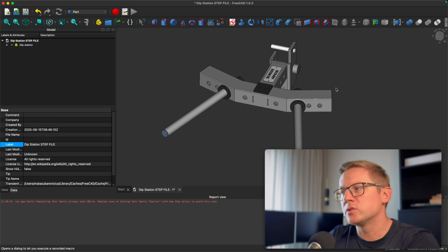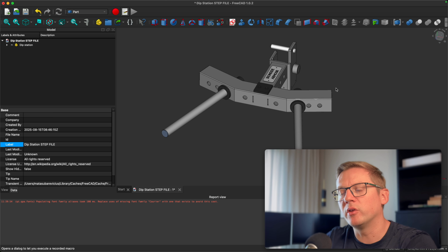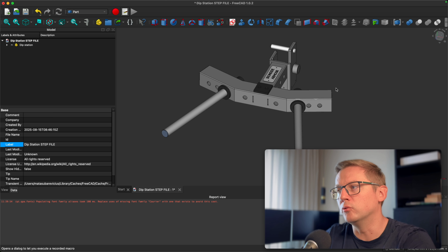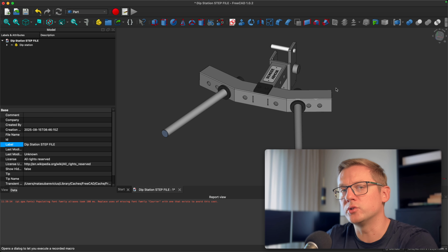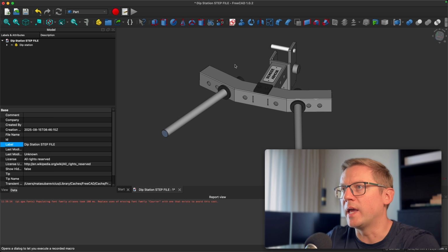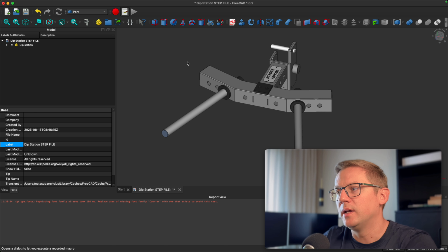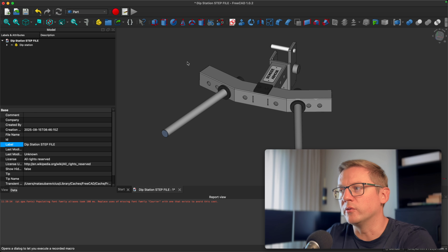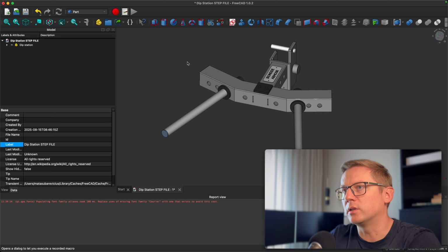In game engines on the web especially, it's very important that you don't overuse the amount of meshes. Thus, we want to keep the amount of meshes that we generate from such a model to the minimum. And to do that, actually, it's best to just group them by materials. In this case, I will just use color to group the objects into logical sets, right? And each color represents a family of objects that will land into separate meshes, and you can then also choose different kinds of tessellation options for those meshes. But let's just start and see what I mean.